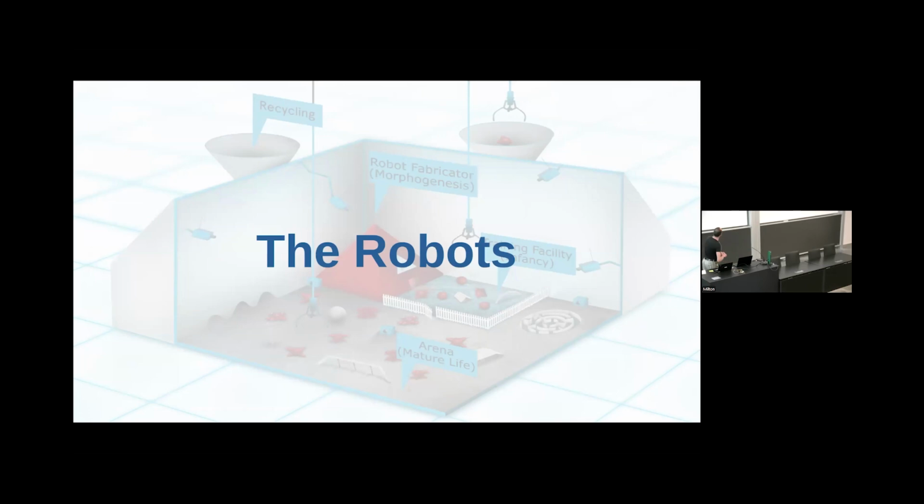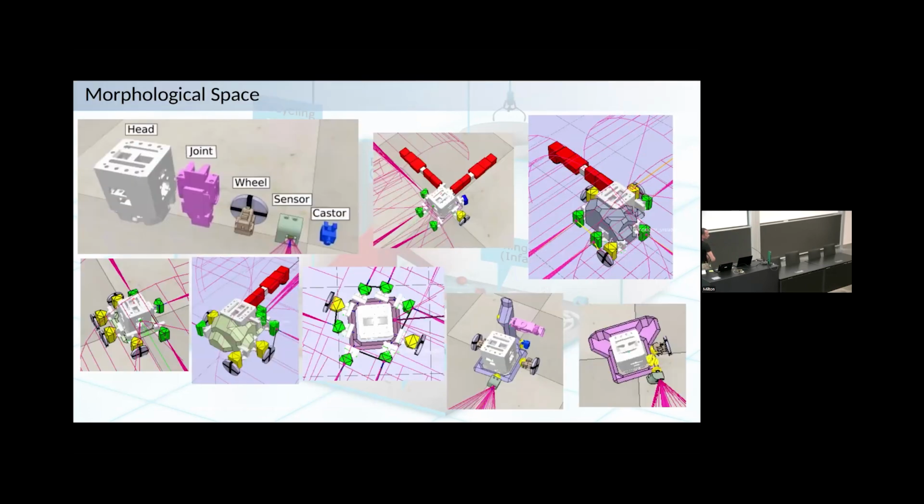So what do our robots look like exactly? In this project we wanted a very large morphological space where we could build many different types of robots, from legged robots to wheeled robots, mixtures of legs and wheels, and put sensors wherever we want. We also had a motivation to move away from modular robotic hardware, which is the most used in evolutionary robotics. Here our robots are composed of 5 pre-designed components, fixed on a chassis which is freeform and voxel-based in simulation.